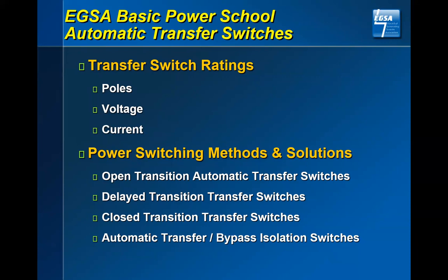Another application of that is when you are dealing with a UPS, uninterrupted power supply, downstream. Many times they would rather see you delay that transition, break the first source. The UPS will acknowledge it's lost power. It'll go into its mode with the batteries. Then you close back to the other source and it returns to feeding the power through the utility side.